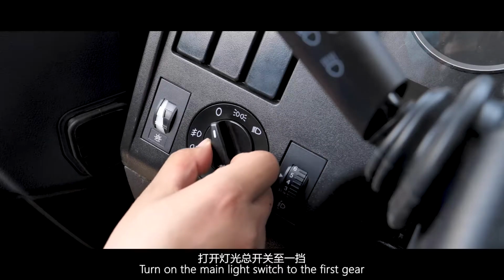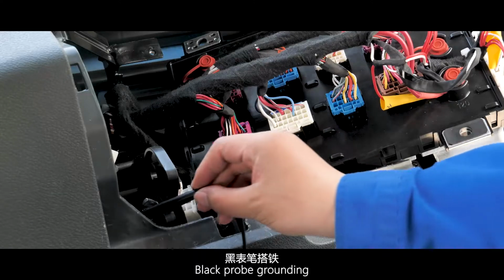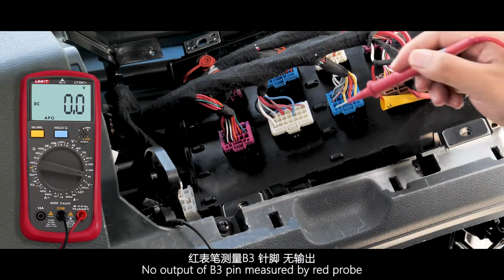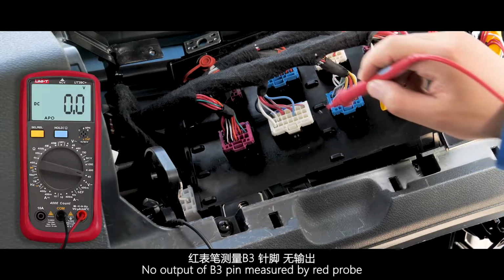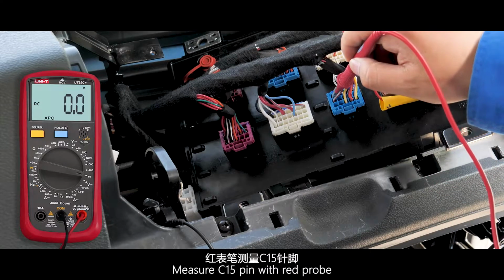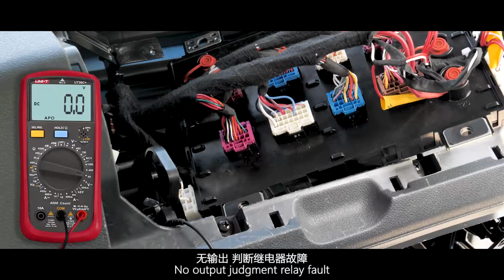Turn on the main light switch to the first gear. No output of B3 pin measured by red probe. Measure C15 pin with red probe. No output, judgment, relay fault.